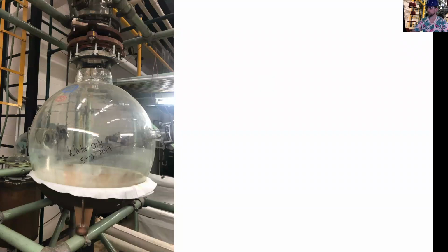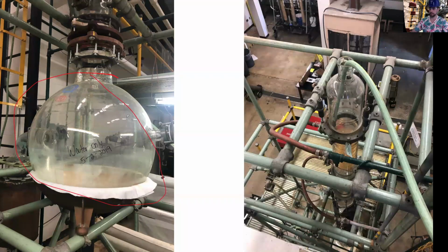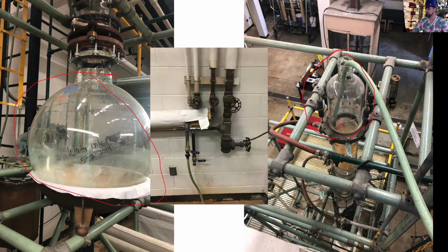So at the base, once you have your cold water flowing, you can fill your unit. Now probably the easiest way to do this is at the top with whatever your mixture needs to be. If you're filling up with water, you can connect the cold water source over here and just fill it down through until your water gets up to your reboiler right here, where you can see a little bit.